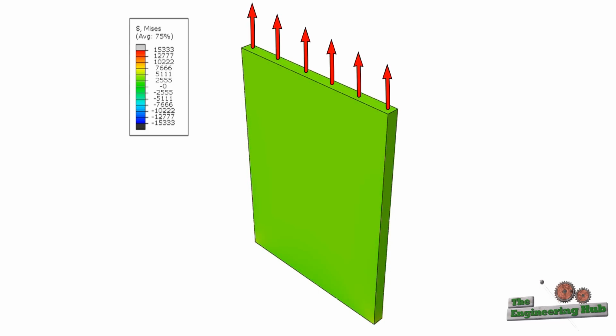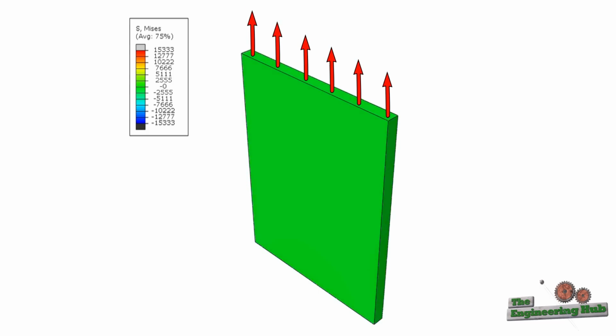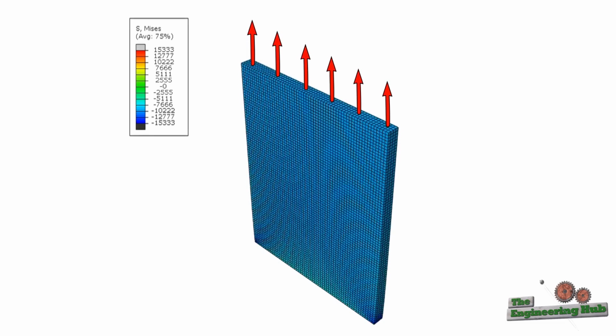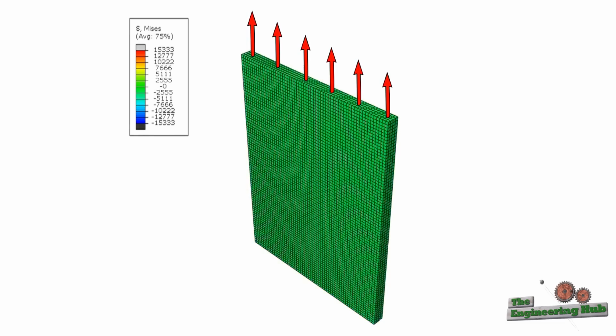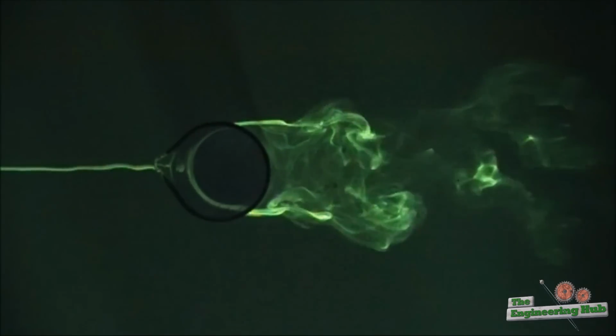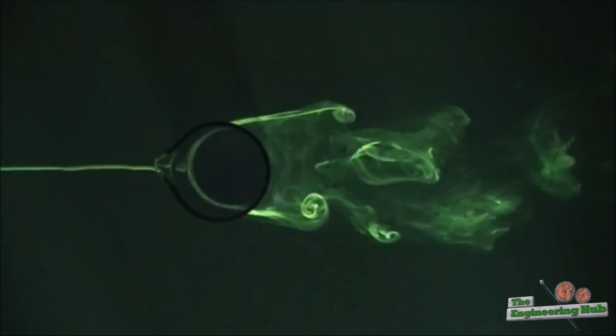It is worth mentioning that the flow analogy works best for plates subjected to a uniform normal stress, whereas in our beam, the normal stress varies linearly and is also accompanied by shear stresses. But regardless, the flow analogy definitely holds some weight, as we illustrated with this experimental campaign.